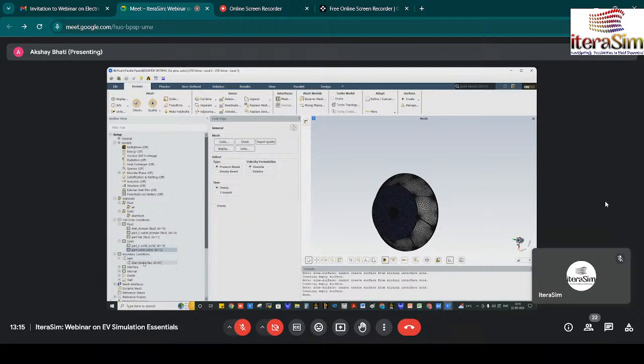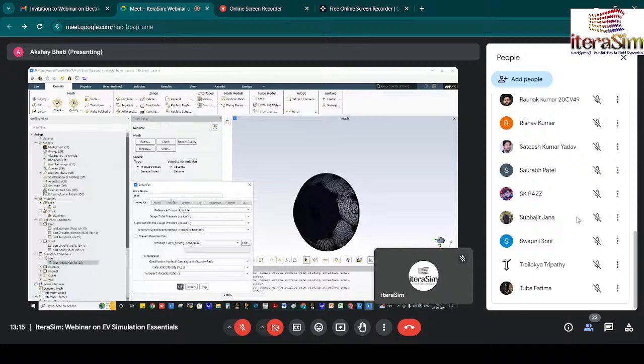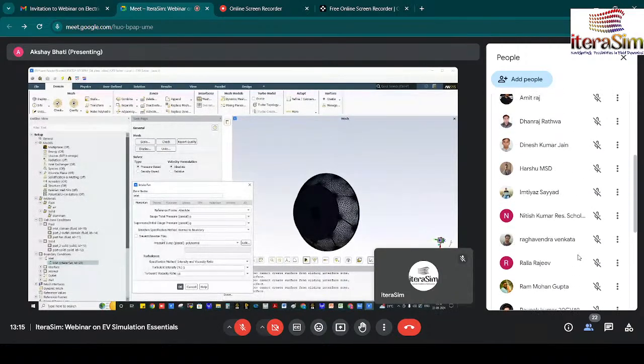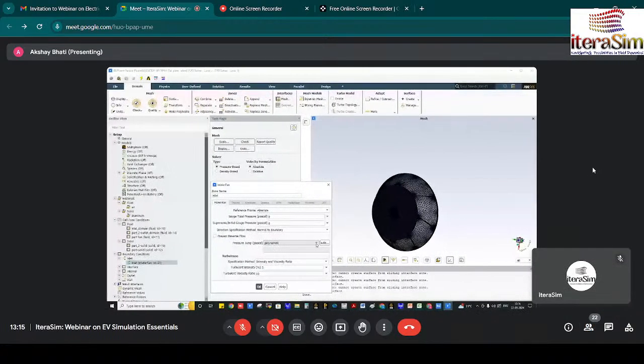And in the inlet part, in Fluent you need to give the type, and here it is the intake fan. So it will take the boundary condition like that, and you need not give anything, because if you give anything here, you are forcing the fan to do this. So automatically, don't give anything. And pressure jump polynomial means there is a relation between the pressure and the flow rate, P and Q. Okay, so basically there is a relation, P and velocity, pressure and velocity.